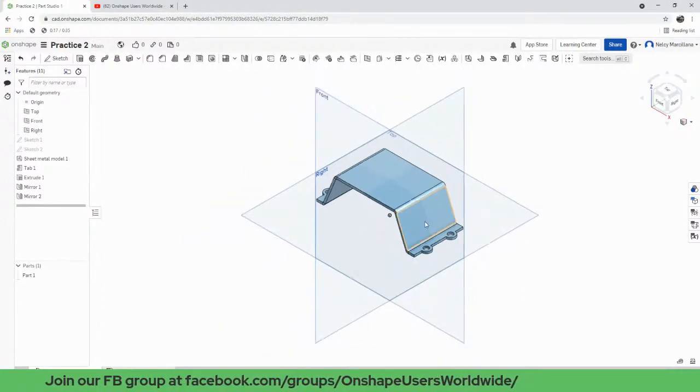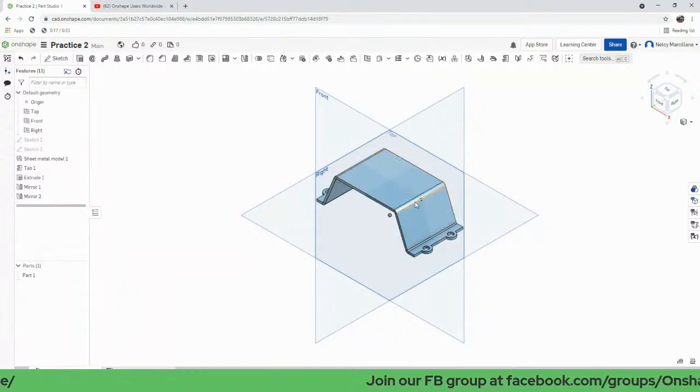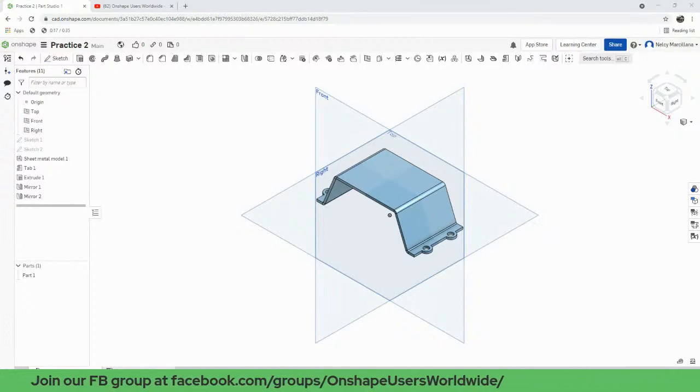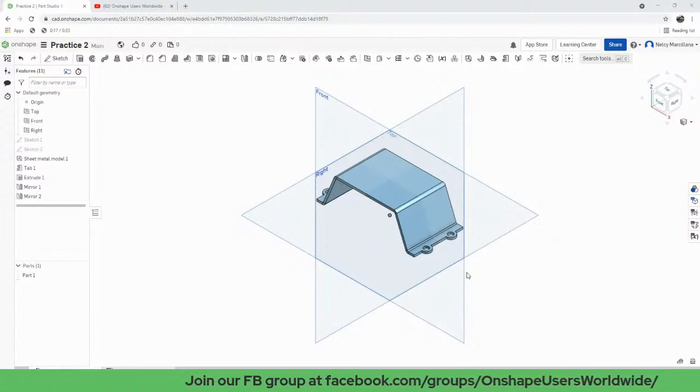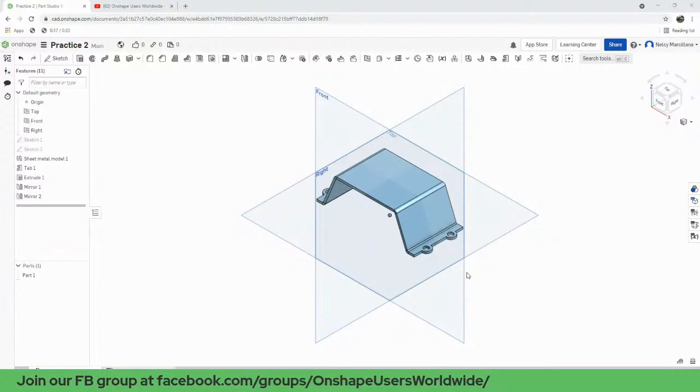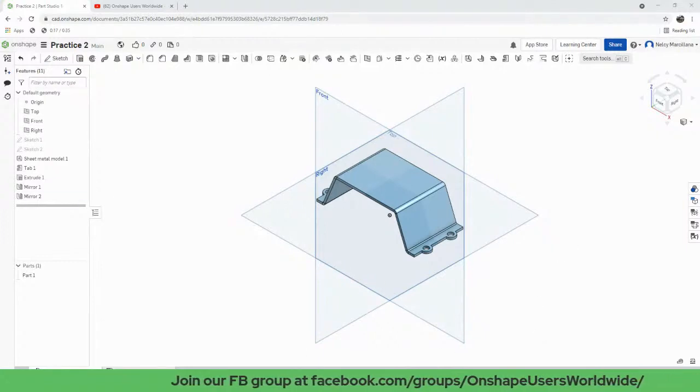Okay. So our next intent is to create or cut material here. To do that properly, let's head over to Sheetmetal table and flat view. This functionality is currently available only in Onshape's browser platform. You can edit an existing Sheetmetal model's bends, rips, and joints, and also view the Sheetmetal flat pattern.